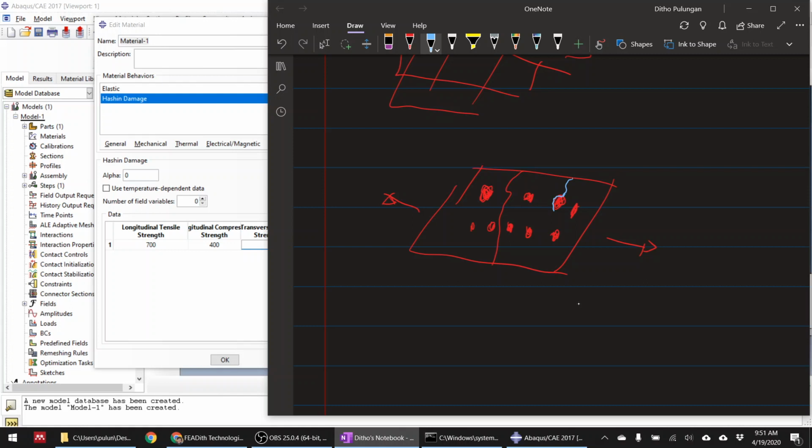So in the interface there will be a debonding. This is the kind of crack that you might see when you do transverse tensile. Because this is interface dominated or matrix dominated, the tensile strength in the transverse direction usually only requires a low stress to make this breakage.